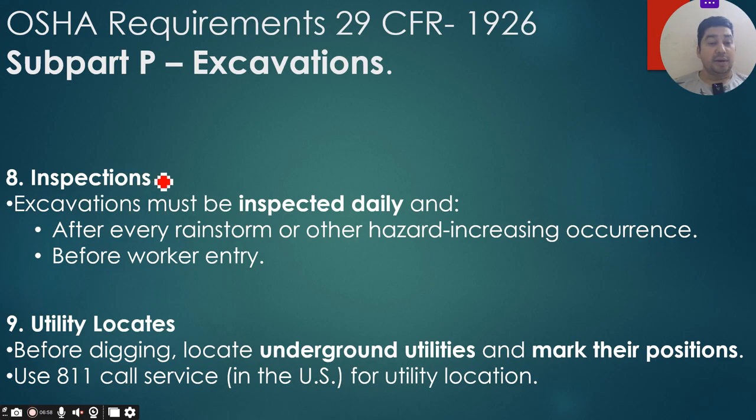Then number 8, inspection. Excavation must be inspected daily by the competent person. Okay, and it should be inspected after every rainstorm or other hazard-increasing occurrence before work entry. So this is the requirement of inspection for excavations or trenches before any work starts.